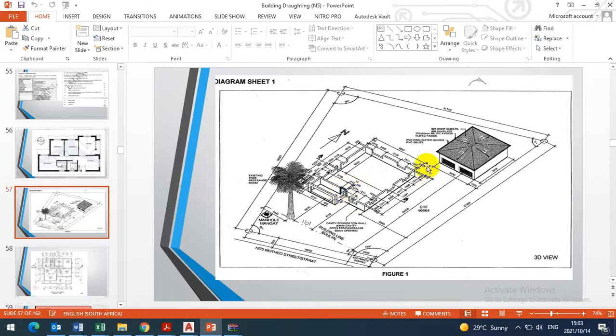On your site plan, you just show us the boundary, external total length here and total length here, back to the garage, in, out, just the external perimeter of the floor to be built. And then you can show your trees and the manhole, the north arrow, which is your true north. Whenever you're viewing like this, it means north is here, south is here, east, west.